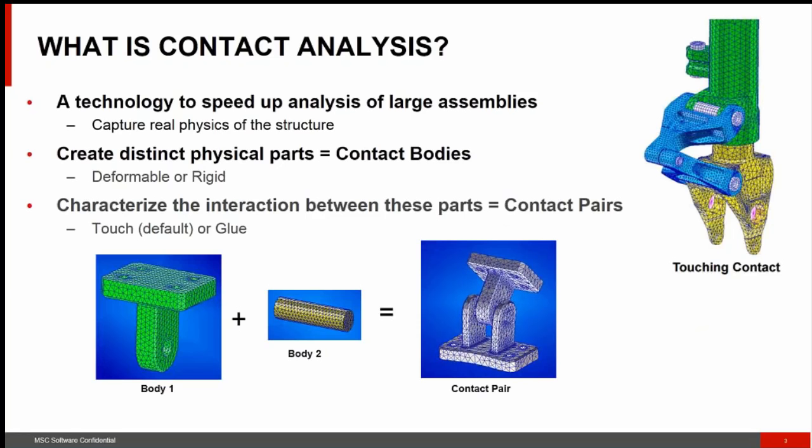From the model assembly perspective, it's very important to have an integrated structure so it doesn't have any rigid body motions and the parts move properly. Many of the parts come from various sources, divisions and departments, and this is a challenge to assemble properly and quickly. This is why the contact procedure can be very useful. This way we can detect the motion of these bodies and parts and easily assemble them without having to deal with node to node connections, like connecting the nodes manually or remeshing the parts.